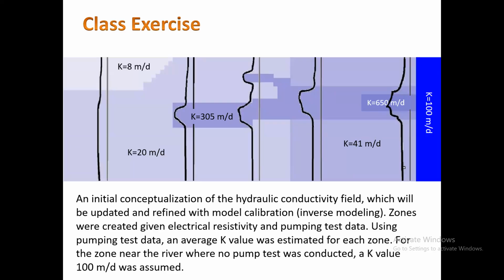Let's say this is my aquifer, it looks something like this, and this is the land surface. And then I have recharge here. This is my water table, with different H values. If I have recharge, H will go up, right?